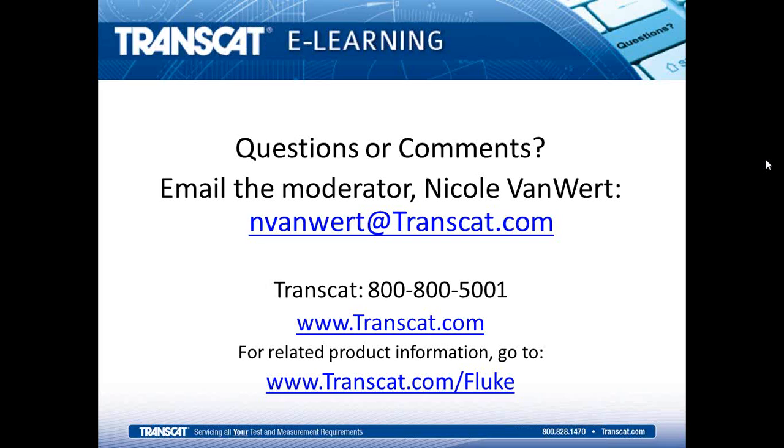Okay, next one. What's the difference in accuracy in a dry block versus an oil bath? Well, it can be pretty drastic. The reason being is the uniformities and stabilities and the errors that we talked about in the slide presentation today are generally a lot smaller in an oil bath. So you could increase the performance of the calibration system by quite a bit by using an oil bath.